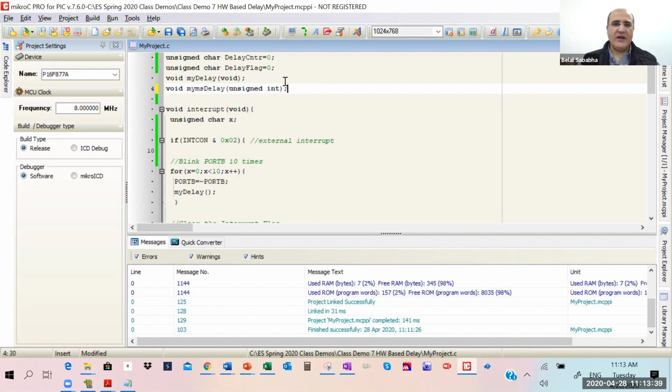If you say my MS delay 1, it will do a 1 millisecond delay, 500 milliseconds, 5,000 milliseconds, up to 65,000, right? That's 65 seconds. Can you do that? Yes.